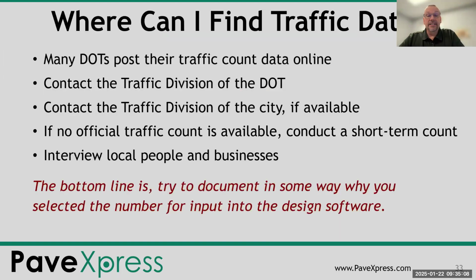The common question is, where can I find traffic data? Many DOTs post their traffic count data online. You can contact the traffic division of your DOT. They typically have some traffic data even on non-DOT roads. If you've got a traffic division of a city, you can contact them.